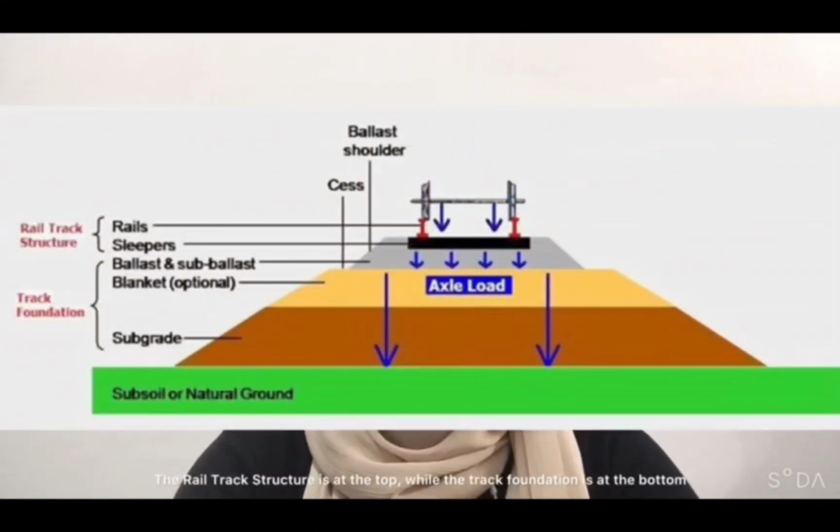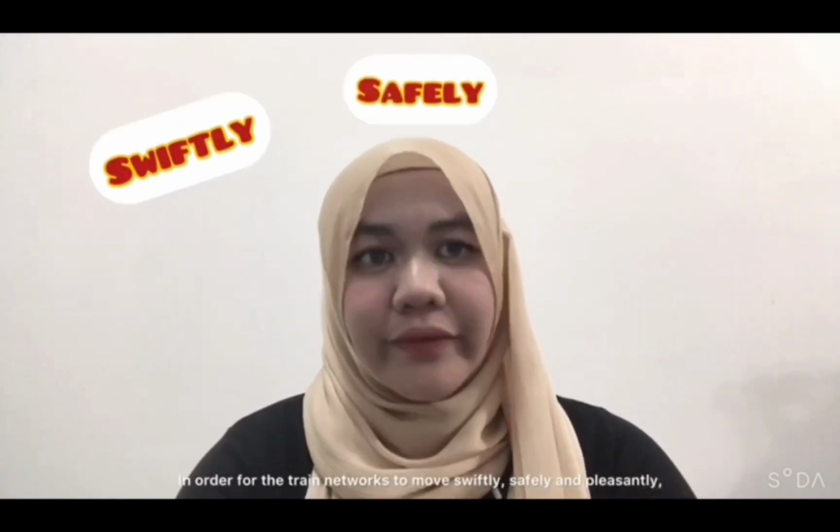There are essentially two components to the construction of the train railway. The rail track structure is at the top, while the track foundation is at the bottom. In order for the train networks to move swiftly, safely, and pleasantly, the train railroad must hold strong when it is passed by the train network. The idea behind this track foundation design is to maintain track stability during the passing of the train network, allowing the railway lines to stay in their original location, avoid swinging or sinking into the earth, and be able to endure the weight of the passing train network.